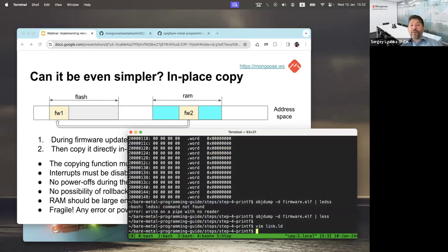And now the only question left is: who copies that data section to RAM, right? Because when we have a firmware on flash, our firmware is a concatenation of text, of functions, and data. But it's a binary, a bin file, just one file, and it resides on flash, right? So what copies that? The answer is the startup code; the microcontroller startup code performs that copy.